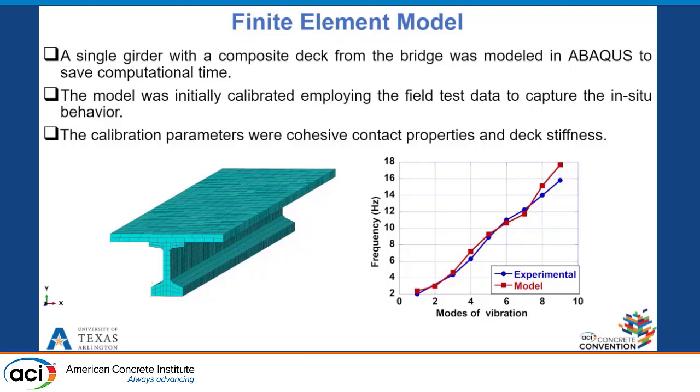In-plane stiffness KSS and out-of-plane KTT cohesive contact shear stiffness of 103 megapascals was assigned to the girder-deck interface to introduce partial composite action. This value was obtained after calibration of the model employing the static load test results reported in the literature. The normal stiffness coefficient, KNN, was assigned a constant large value of 6,895 gigapascals, since only shear failure between the interfaces was modeled to introduce partial composite action.